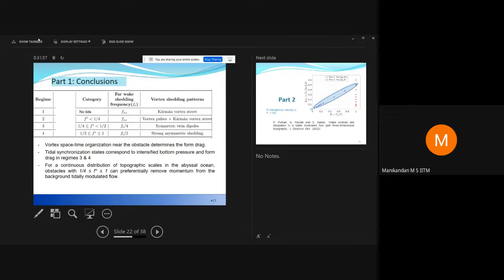So if this cone was very long, would that frequency still be the same? Because the local Reynolds number is changing, yes. So let's assume that the Reynolds number is large enough. For a cylinder, once the Reynolds number becomes large enough, the sensitivity to the Reynolds number is small. That said, people have done experiments with very tall cones, and there they actually see step changes in the vortex shedding frequency. But there are very few experiments like that.